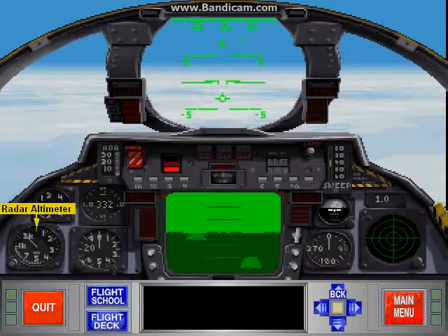The radar altimeter uses the terrain-following radar to display above ground level altitude. This figure is the amount of distance between you and the ground and should not be confused with above sea level altitude. If you are flying over a mountain, there is a significant difference between sea and ground level readings. Above sea level altitude is measured by the altimeter.